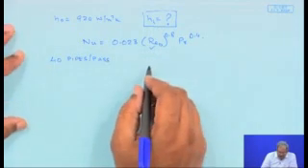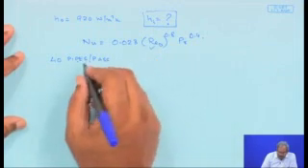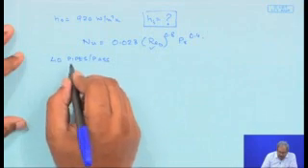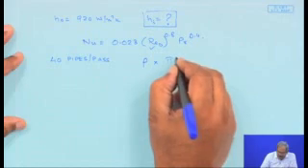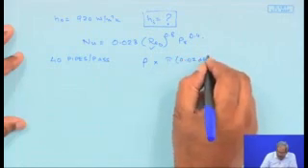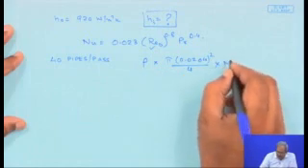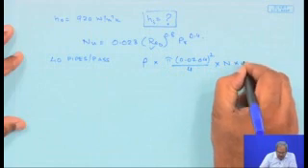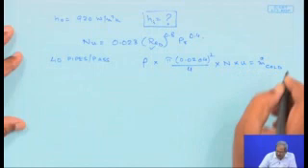If I try to find out the mass flow rate through all these 40 pipes in a pass, which is rho times the cross sectional area of one pipe, pi d square by 4, multiplied by n number of such pipes multiplied by u, this must be equal to m dot of the cold fluid.